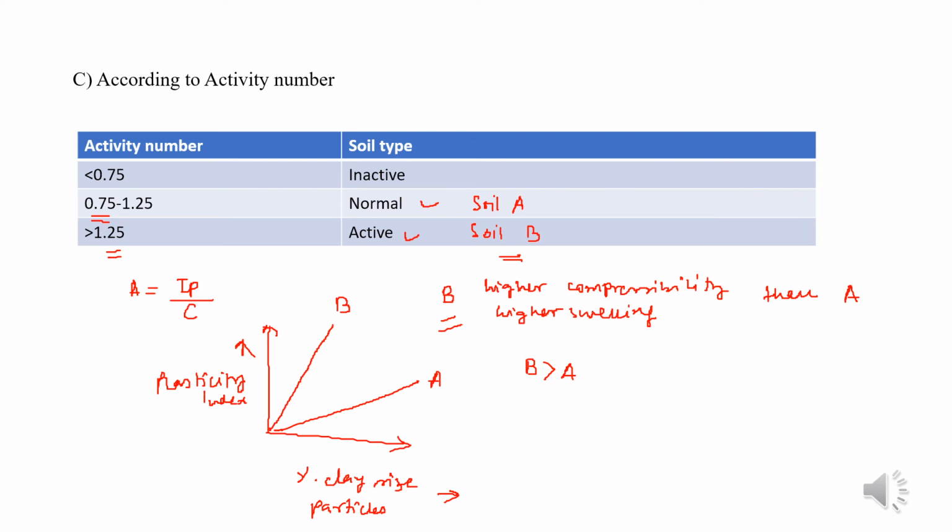So a study of the plasticity index in reference to the liquid limit of the soil can help us determine the type and nature of the clay, as the liquid limit and the plastic limit both depend on the amount and type of clay present. We have already seen the liquidity index is between 0 and 1. In that case, the soil will behave in a plastic state.